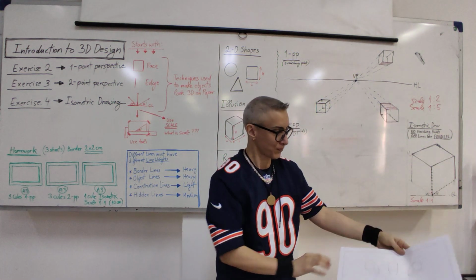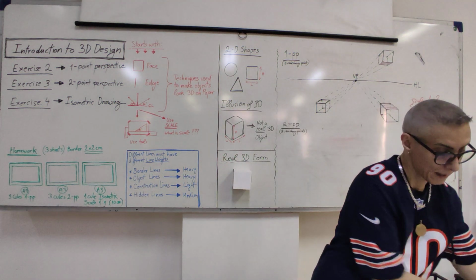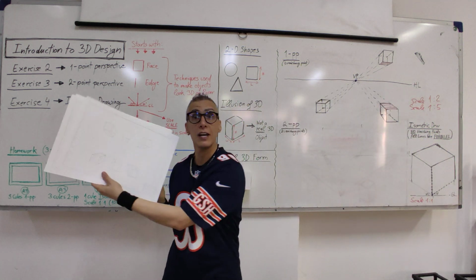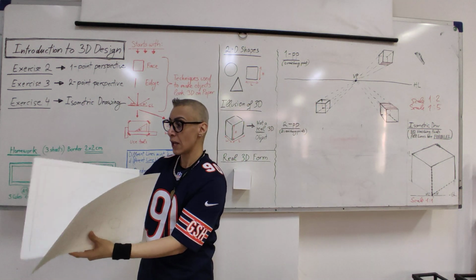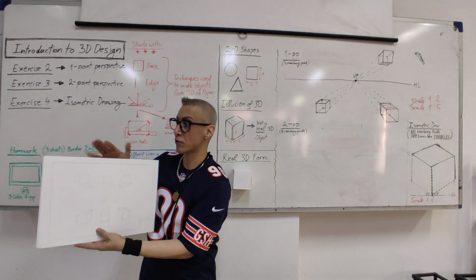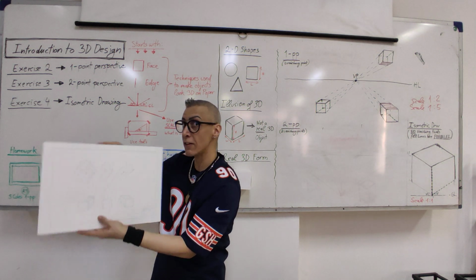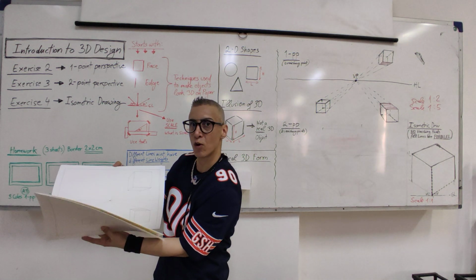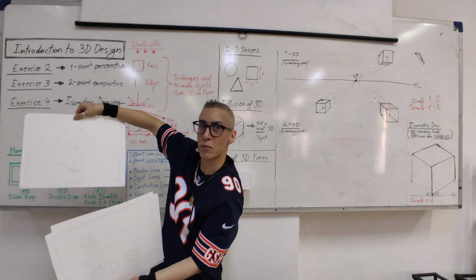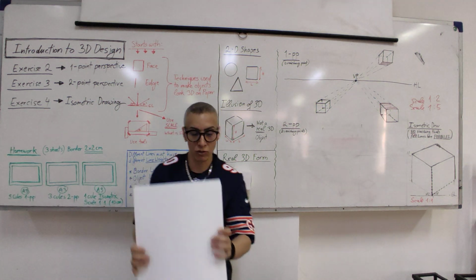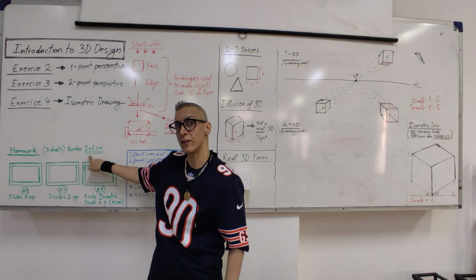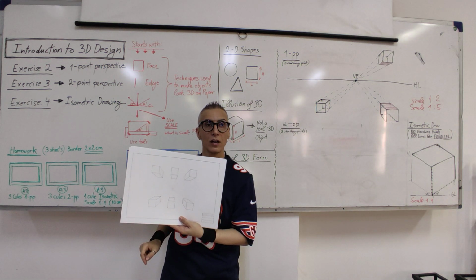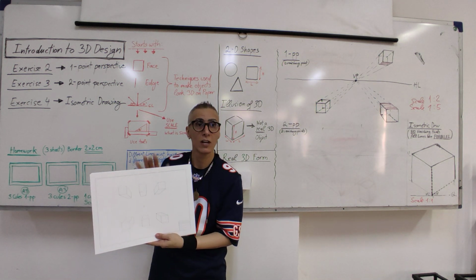Great. Now from now on, because we will draw on A3 Fabriano, which is this size, which I mentioned before. Be careful of the A3 plus. I don't want to see that. Okay, A3 exactly, which is 2 times the A4. All of them will have the same border. Do you see any of these drawings? They have the border. The border is how much? 2 by 2 centimeter. So 2 centimeter from here, 2 centimeter from here. Not 1.5, not 1.8, 2.